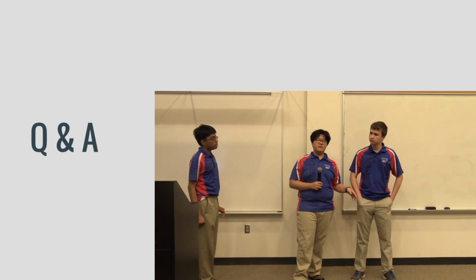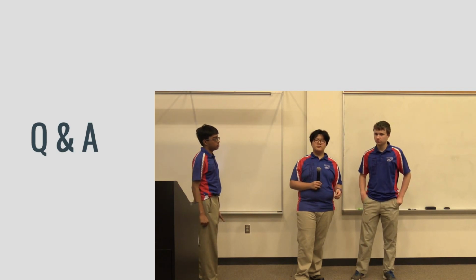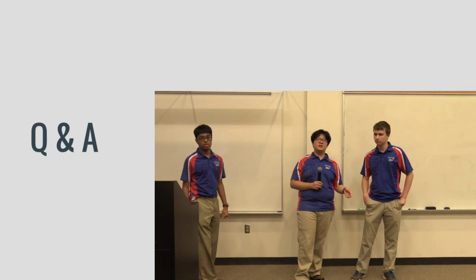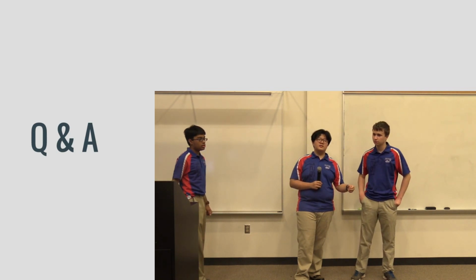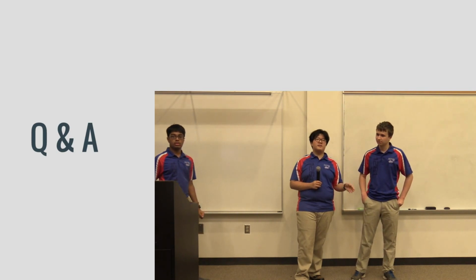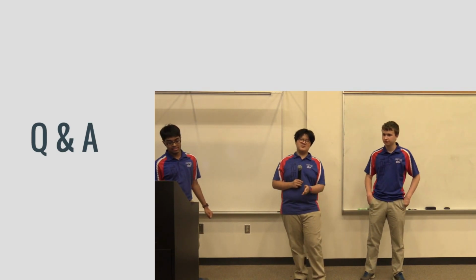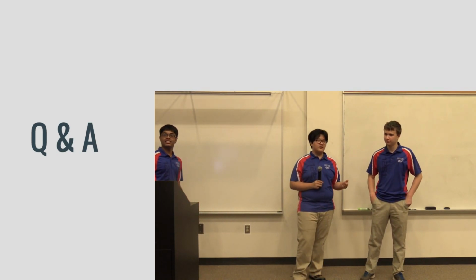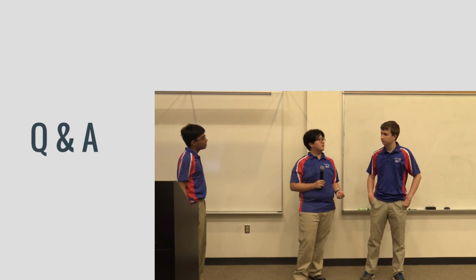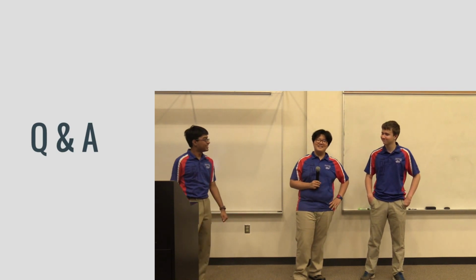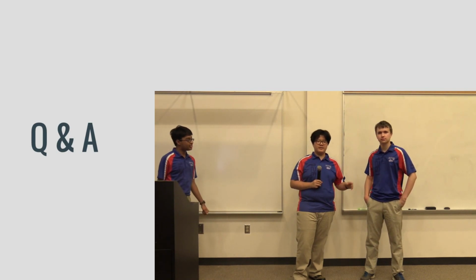You could do that for Microsoft webcams, but Microsoft webcams are weird because sometimes you start at a 0 value for exposure and it's really dark. You slowly increment, and it gets brighter, but then it gets darker. You set it to 1,000, then it gets super dark, and you set it to 500, it's super bright. It's weird. Logitech cameras are a lot more simple in that they actually follow that spectrum. Specifically, the cameras that Chris and I worked with were the Logitech 620s, I think. It started with a 6. Those cameras actually followed that whole exposure setting code.